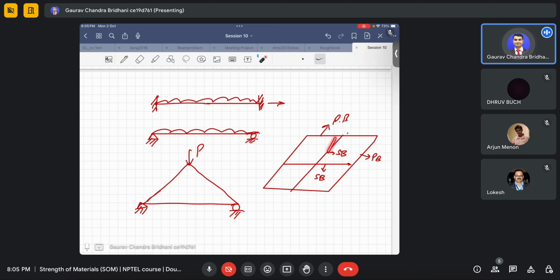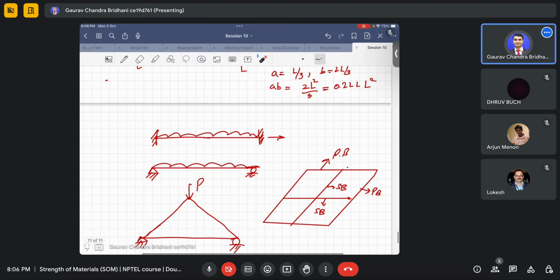What if I make this secondary beam fixed? So this will be fixed, this will be fixed. That means there will be a movement. Now this movement will be a point movement to this beam, and I have to analyze it. I have to put some extra arrangement there to resist that point movement. But if rotation is allowed, then it will be allowed to rotate there. So these types of things come up.